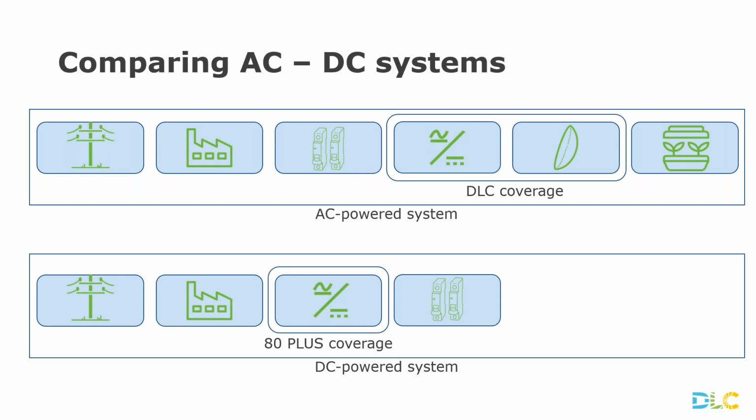Then we go back down into the wiring system. So you have special DC circuit breakers and special DC wiring cabling that oftentimes are thicker than normal AC wiring because of the current losses you have to be worried about. But again, if you are installing these systems to National Electrical Code, you will, for thermal safety reasons, not be exceeding 3% loss in a branch and 5% in the overall system. So again, that's equivalent to what the wiring losses should be in an AC powered system.